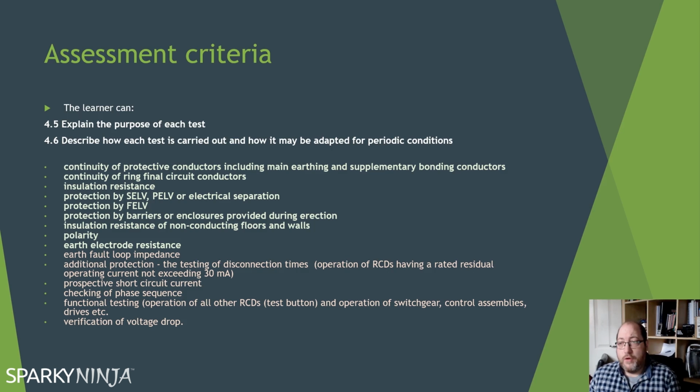It must be clear. From an initial verification perspective though, you'll verify the phase sequence energized at the source of supply when you do your Ze and your PFC, but you won't verify it energized throughout the rest of the system. Some people would say, oh no, you could do the phase rotation verification when you do the R1 plus R2 part of your continuity testing. By doing L1 to L you can do R1 to R2 of L1, then you can do R1 to R2 of L2, then R1 to R2 of L3. So you can identify L1 from L2 from L3 at that point. That's what they say. From initial verification perspective, I guess that makes sense.